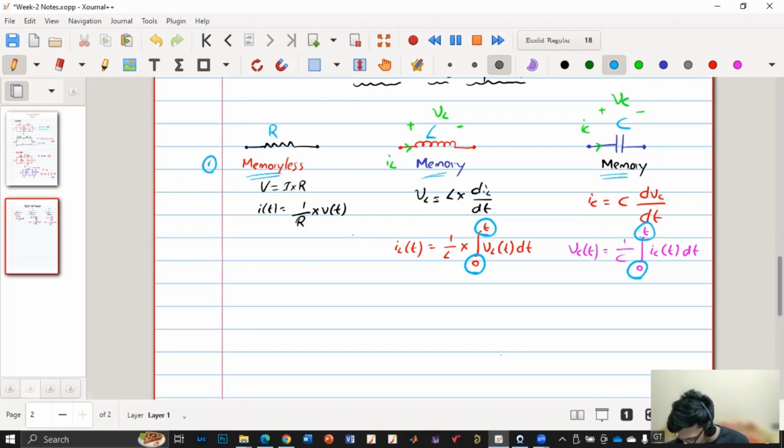Now we are going to point 2. Whether the current in the resistor can change instantaneously. In here, current depends upon the magnitude of the voltage. If the voltage changes, then the current also changes instantaneously. So there is a possibility that current can change instantaneously. Like in this moment, current can be 0, and in the next moment, the current can be 5 amperes because the voltage is changing. It is a linear relation between voltage and current for resistors, and current can change instantaneously.